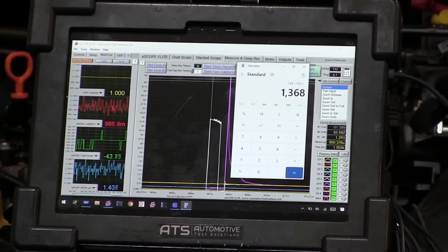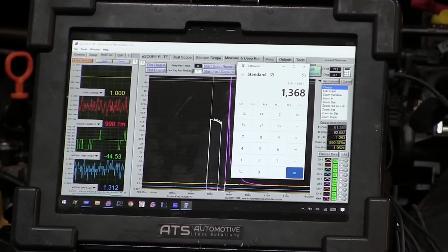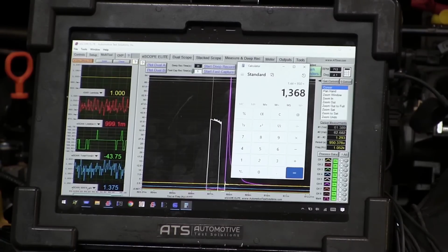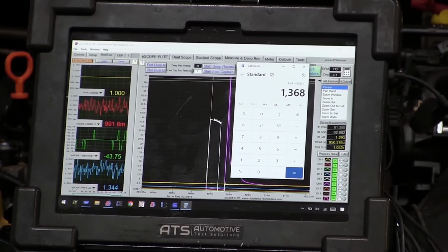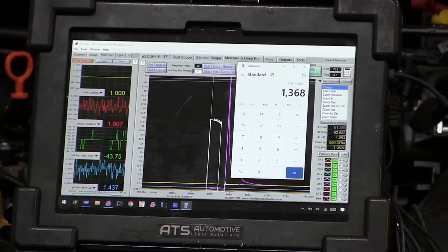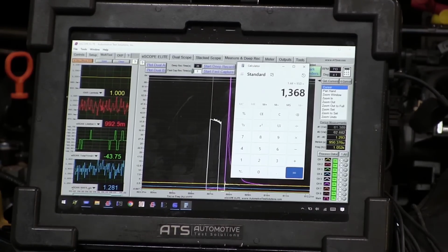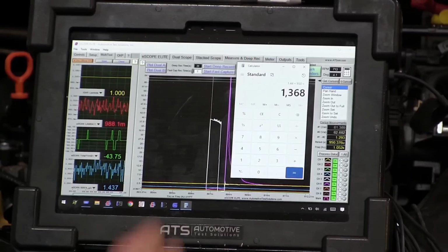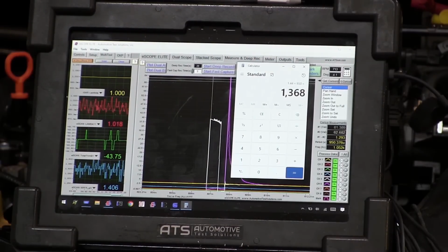I'm no Honda expert, but I know where I've been burned on a lot of cars. So I'm going to go get an enhanced scan tool, and I just want to see if I have any alcohol content on a Honda. Because that would be something that could get that base equation really high, if it thought there's a bunch of alcohol in the fuel. So let me go get that other scan tool and let's look through the data stream.